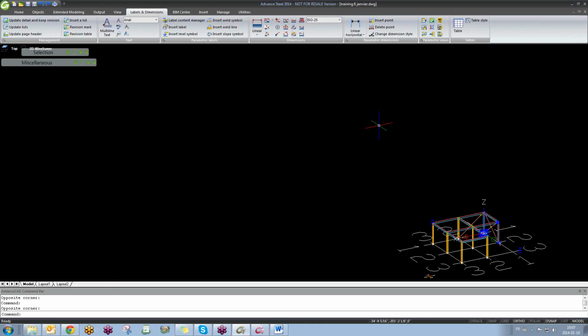Yeah, and I think you can do that, Tony, as long as you turn it into a DWG. Right, and then just bring it in on that. Yeah, instead of an SPF, just make it a DWG, and then you can insert it. Because basically the 2D drawings in this are just DWGs, so it's just like AutoCAD. It's just like bringing in a block in AutoCAD. Right.